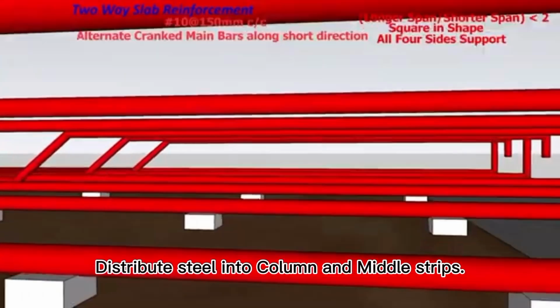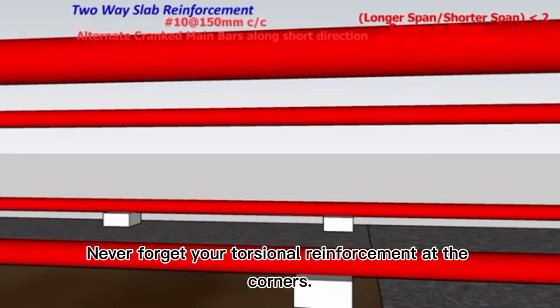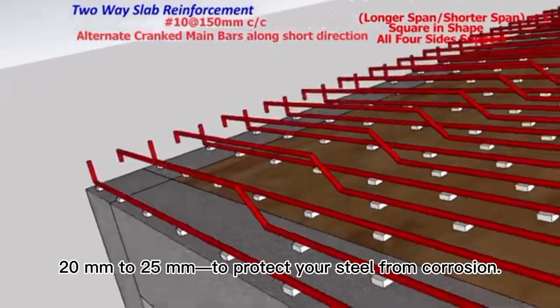Distribute steel into column and middle strips. Never forget your torsional reinforcement at the corners. Ensure a minimum concrete cover, usually 20 mm to 25 mm, to protect your steel from corrosion.